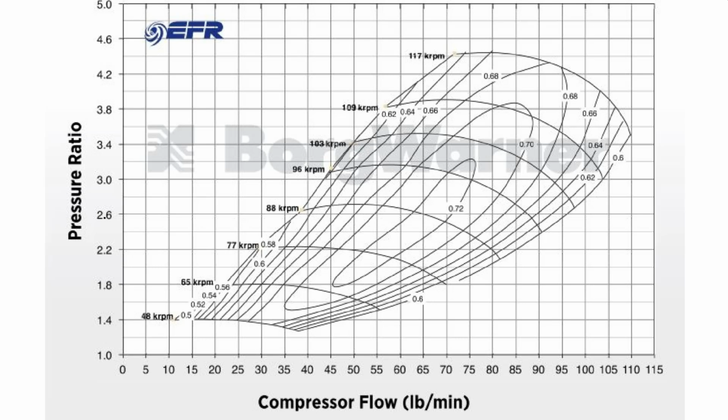And so if the ECM detects that it's operating in these regions, it may take measures such as a fuel derate, or in the case of VGT, changing the VGT such that we're out of that region to protect the turbocharger.